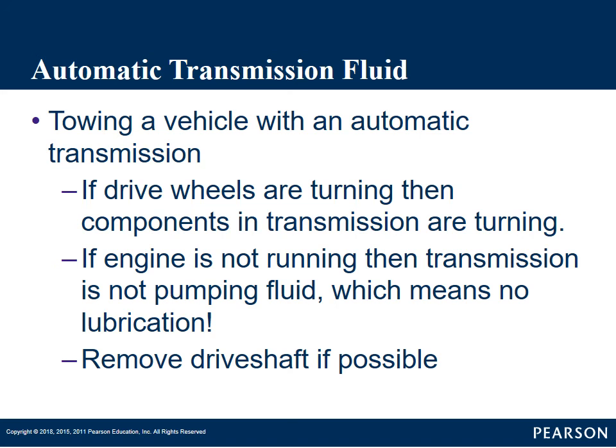Some four-wheel drives, depending on the construction of the transfer case, you can put the transfer case in neutral, then go ahead and tow it. All-wheel drive vehicles, you're going to want to get it on a flatbed truck and tow that.